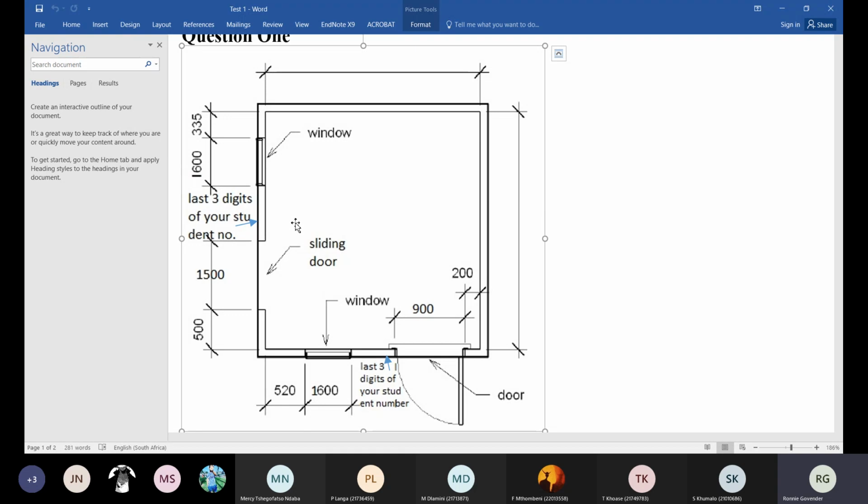So basically 9.8 courses there. And I told you in class, when you got 9.8, it's actually 9, because you're not going to put 1 on the top there. So 9 plus the 1 that you got at the bottom. In other words, you need 1 right on from your floor going up. So that would have actually been 10 courses really. You would have had 10 courses along the perimeter up to ceiling height.